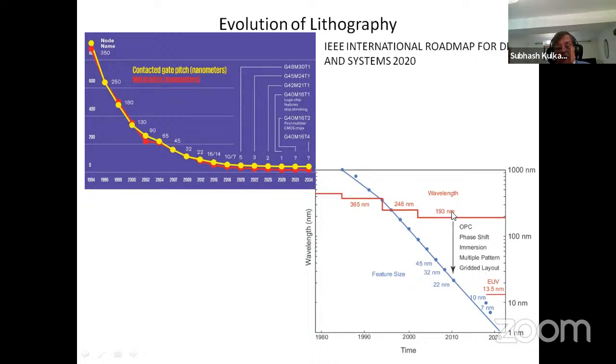And the same lithography machine, for example, immersion. In immersion, in the lithography machine, you have a water lens. Water is flowing in the machine and the optics is built around it so that the numerical aperture is increased, because water gives you a much higher numerical aperture than air. And you can go down in terms of resolution.